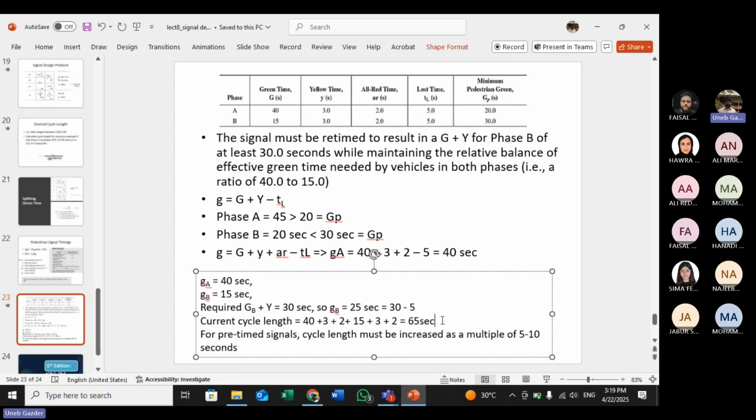Remember yesterday when we were calculating the signal timing, we were taking the ratio of the flow of one phase upon the total. So there's a balance. We are maintaining the balance, so that if you combine the flow of each phase, it will be equal to the total. If you just change one phase, you will not achieve this. After changing only one phase, the combination will not be equal to the total. In the end, the total should remain 100%. Agreed?